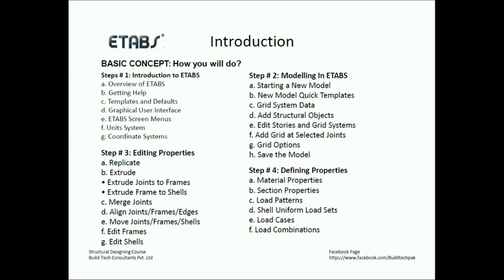Like if you have a building with the same floor plans all over the 15 floors, you just need to adjust one plan and let Etabs know you have 16 similar floor plans, so it will automatically create 16 similar floor plans for you. The good option in Etabs is that it has a replicate option. You can completely select a floor, or even select a few columns, a few beams, and replicate them in the next stories, the upper stories.